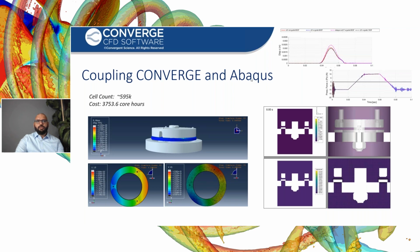What this can do is that every time step, CONVERGE calculates the fluid forces on the solid object and transfers that information to Abaqus. Then Abaqus will calculate the deformations and get that information back into CONVERGE every time step. So just to illustrate it, here is the same plate valve case that we simulated just using CONVERGE's rigid body and contact modeling feature.